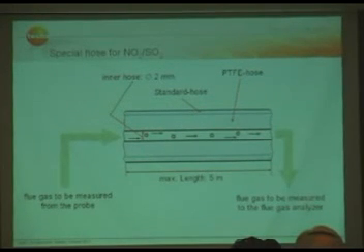In the past, as we developed our flue gas analyzers, we figured out, depending on the regulatory in different countries, that heated lines are required and necessary just to prevent the absorption of NO2 and SO2 during the measurement. And then, after talking to some customers and being on site and performing measurements, we figured out that heated lines are very sensitive.